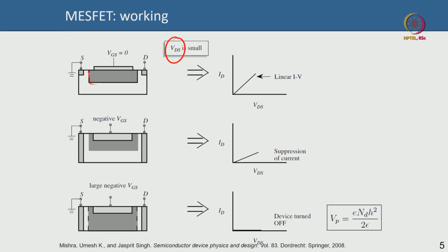At 0 voltage on the gate you have certain depletion, this is the channel which the electrons will go in, right. As you apply more and more negative voltage, this channel will become less and less, and eventually the channel will turn off, correct. So, this is at low VDS, this is all at low VDS. So, this is your output characteristics, you are plotting the output current ID versus the output voltage VD in all of this, you are plotting the same thing.